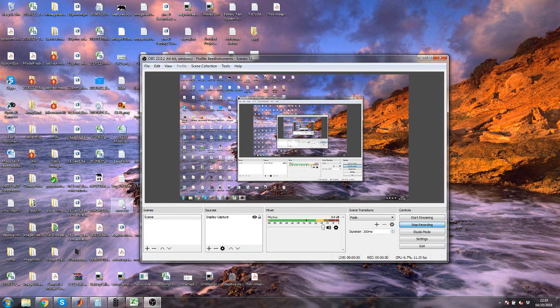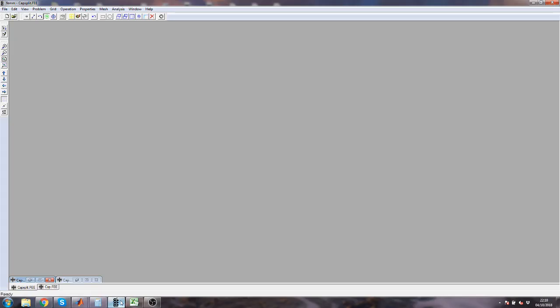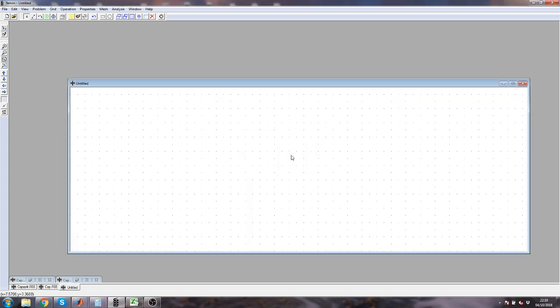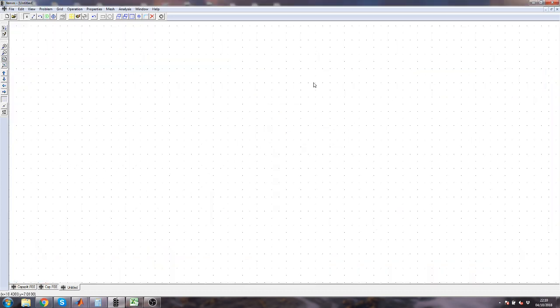So I'm going to use FEMM for this because it's a planar problem, and FEMM is quite quick to set up for this sort of thing, and it's feature rich considering how easy it is to use. So you can download it from femm.info, and there's a good manual online. There's plenty of tutorials as well, but just to solve this problem we have a new electrostatics problem, and that will give us where we draw out the problem.